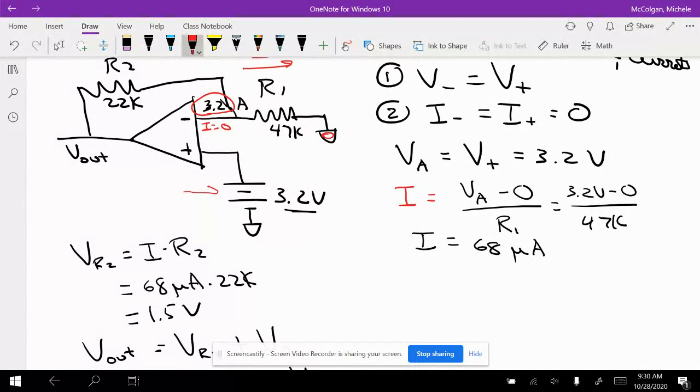I know that because the signal here, this voltage, is considered my signal. It can be a DC voltage in this case, like a battery, but we could also have a time varying signal that would look like this on the input. So to see whether it's a time varying or a DC value, we look at what input it's going to. And so here it's going into our non-inverting input. And if that's the case, we know that our non-inverting op-amp should have a positive V out. And so most of the time that means that our V out is going to, the current is going to flow this way through the resistor.